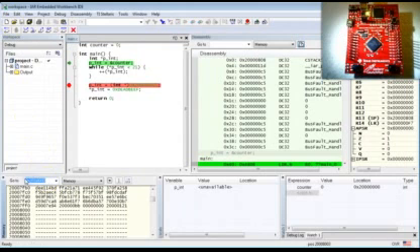Paste the starting address of GPIO F to the memory view and watch what comes up. Whoops, this address range of GPIO F advertised in the datasheet appears empty. If this happens to you, don't despair. The typical reason is that the hardware block is switched off by default to save power.